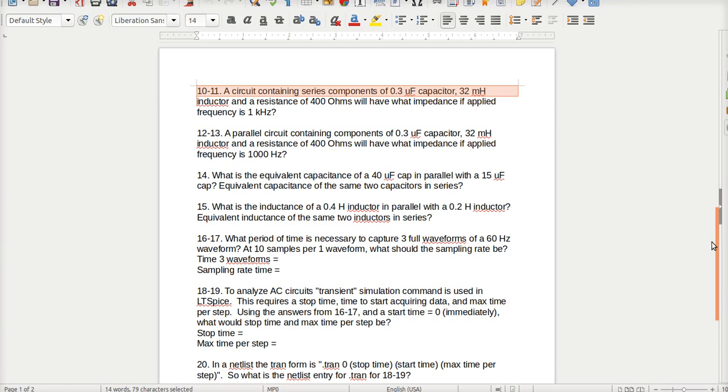The resistor vector points along the positive x-axis. The inductive vector points straight up, and the capacitive reactance vector points straight down, and it's a vector addition problem if they're in series. If they're in parallel, you would find their vector values, their capacitive, their reactances, and of course the resistance, you don't have to do anything, it's given. But these are now vectors,